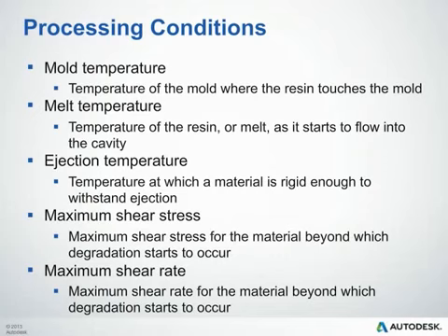The shear rate is how fast those layers are sliding past one another. These can lead to shear heating. They can also lead to degradation of your material's properties, as I had previously mentioned. So these are two important values that the software will make you aware of, but you also want to know what the proper values are for the material you're working with, since they will vary.